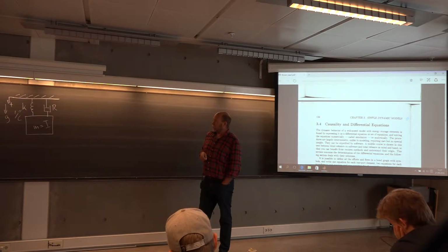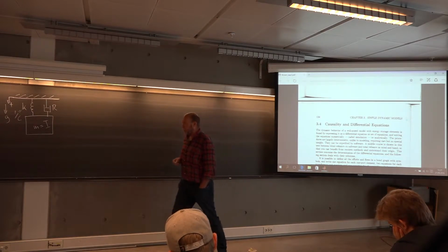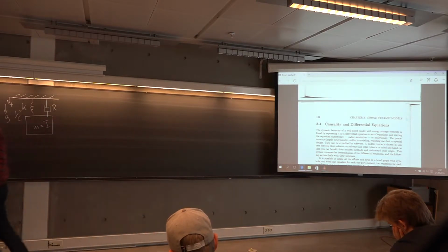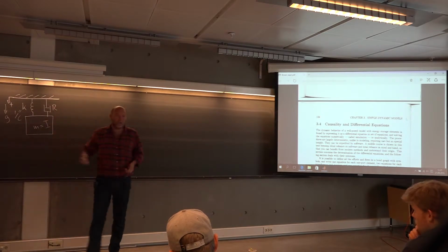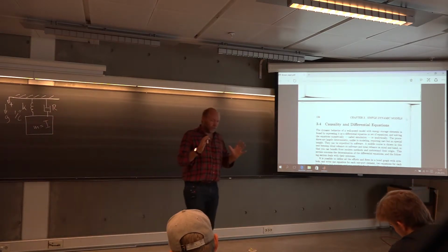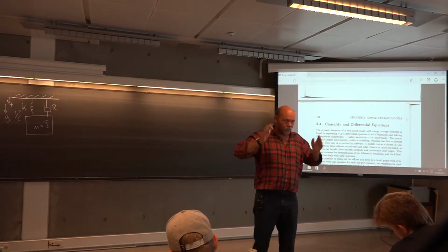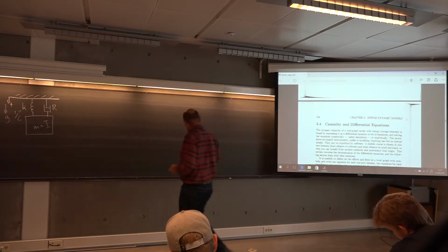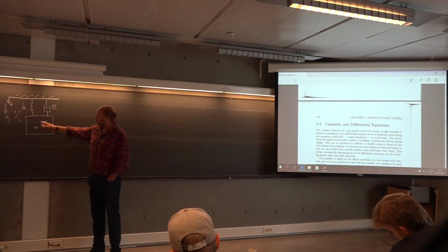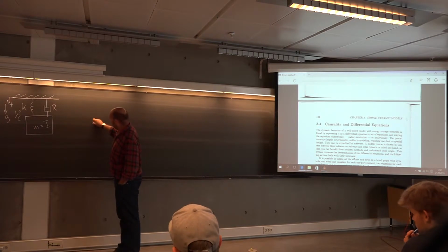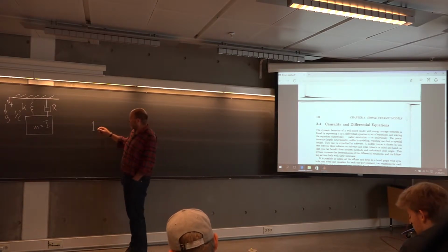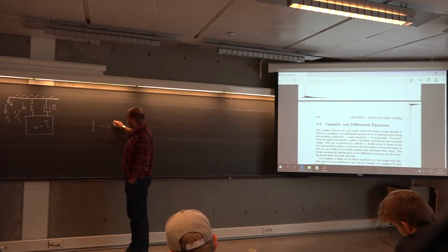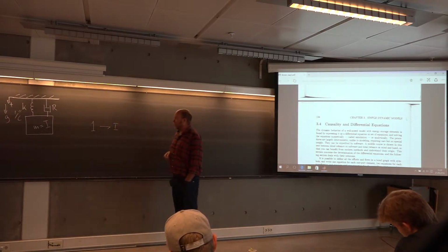So now let us try to make a bond graph of this problem. I start with the mass. The mass, that is one solid object moving with its own velocity. So I will use a one junction on top of him. And this one junction has mass attached to it, so I just hook on the inertance directly.